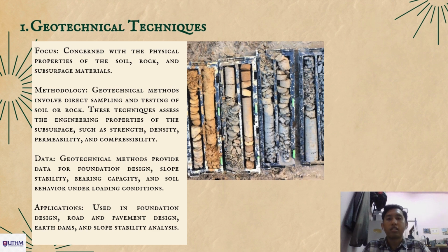In site investigation, there are two types of techniques, which are geotechnical techniques and geophysical techniques. The first one is geotechnical techniques. Geotechnical techniques are concerned with the physical properties of the soil, rock, and subsurface material. They also involve direct sampling and testing of soil or rock.